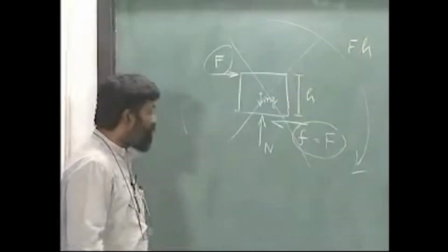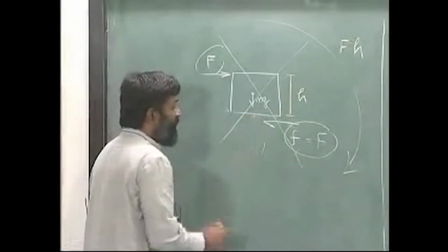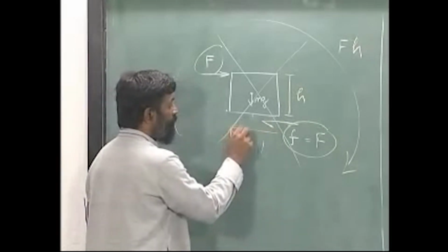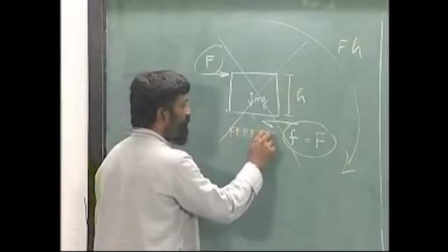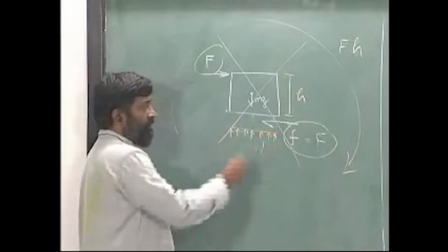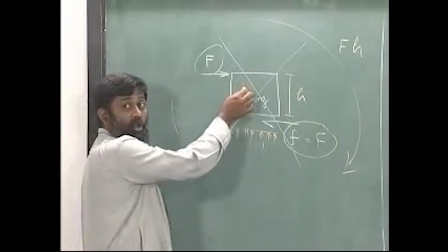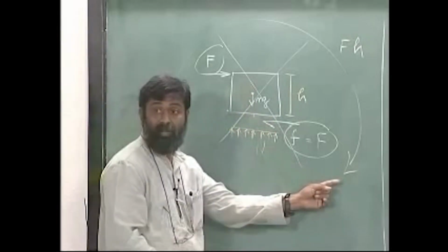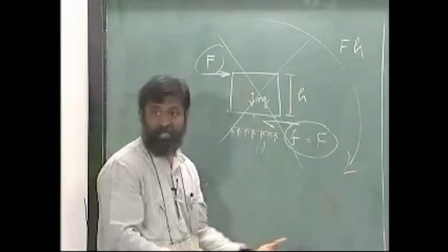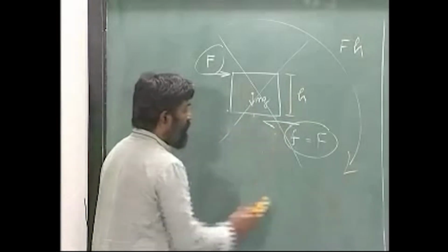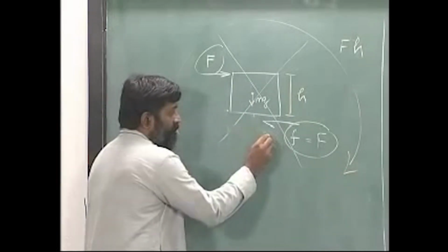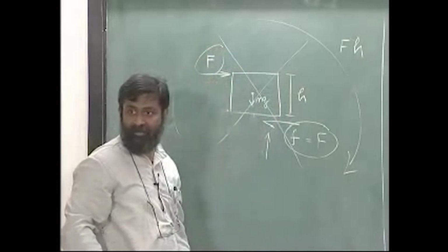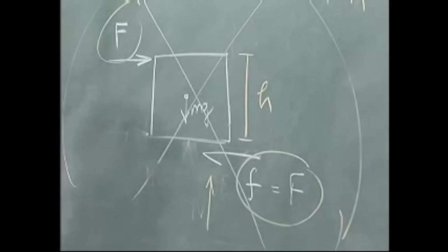The resistance is offered by a variation. For example, if I draw the normal reaction to be uniform like this, then its resultant is along mg. Actually, since I have to offset this couple in the static case, n will shift like this, so that this will form an opposite couple, alright.